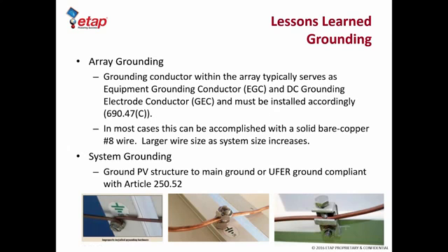On the array grounding, the equipment grounding conductor, which is EGC, and the grounding electrode conductor, GEC, should also be installed appropriately. 690.47(C) tells us that.